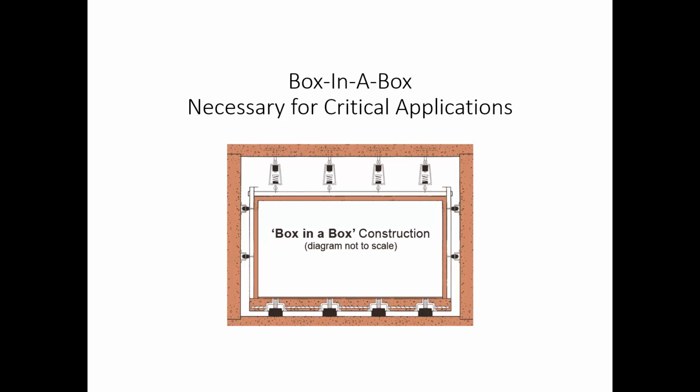In this case, for that nightclub, if you're starting from design, it'd probably be better to build a box in a box. So here you have the structure of the building. And then here you have the space within which your movie theater, your nightclub, or whatever that's going to be loud is going to be located. You have the floor isolated.